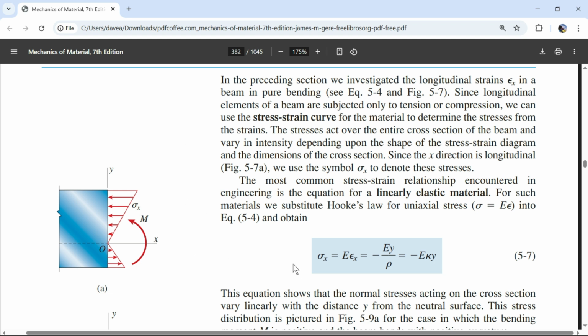And so what we need is the pressures. The pressure is going to be the same, 58,000 psi. That is going to be the same as that thing stretching 0.2%, or 0.002 times its original length.